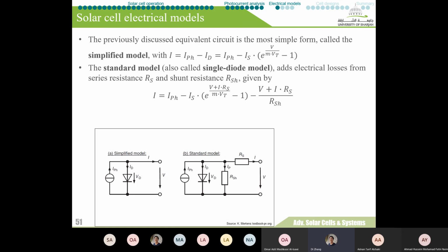What are the typical circuit models we can apply for a solar cell? If you recall from the solar PV lecture, we started from the simplified model. We have one current source here to represent the generation of a photocurrent, which is related to our generation rate from the equation before. And for the PN junction itself, we have a semiconductor diode here to represent it. That is our simplified model, and this is the equation we have been using in solar PV.